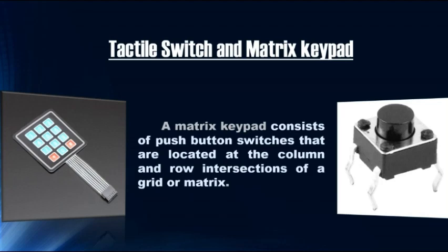In our microwave oven project, tactile switches were strategically placed to control various functions like power, timer setting, and cooking modes. We learned how to connect and program these switches to respond to user input accurately. We gained a basic understanding of how tactile switches work, including their electrical characteristics and the need for debouncing.